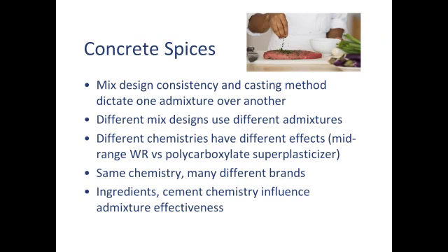You may not know exactly how much you need until you start tasting it, which basically means you can't put the salt and pepper in the eggs up front because you don't know exactly how much you're going to need, depending on who's eating it, if you're making it for somebody else. Some mix designs have, say, super plasticizers as part of the formula up front, whereas other mix designs add it at the tail end after the concrete's made, just to tweak and modify and shift the consistency of the mix in a subtle way. So you can use them both ways. So our admixtures are our concrete spices, and different mix designs and different consistencies and different casting methods may dictate